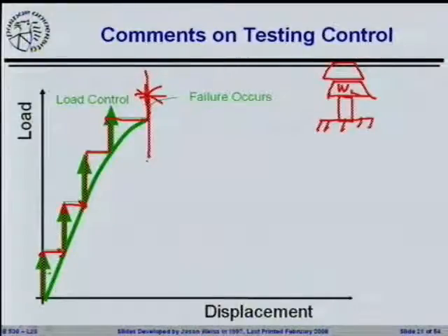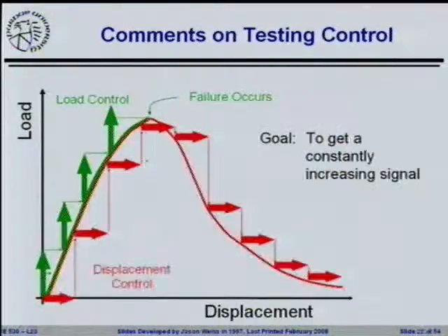Now, I would say there is an alternative, a different way that you could actually test the cylinder. Instead of doing the test like we talked about before, where you're simply applying a weight to the top of the sample, you could say, I'm going to go a little bit differently, and apply a 1/4 inch displacement to the sample. And I'm going to measure the force that it took to do that. Apply another displacement. Measure the force. Apply another displacement. Measure the force.